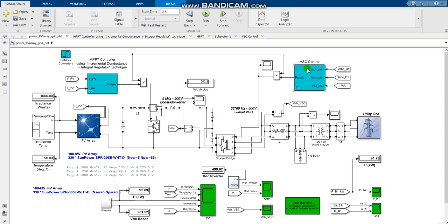Now, this VSC control here controls the pulse width modulated signals that are used to trigger the gate of each IGBT. That gate signal controls when the IGBT is both on and off. So we can see here that we have around 500 volts input into that DC, and we want to convert it to around 260 volts RMS AC here, which is what the transformer is designed for.